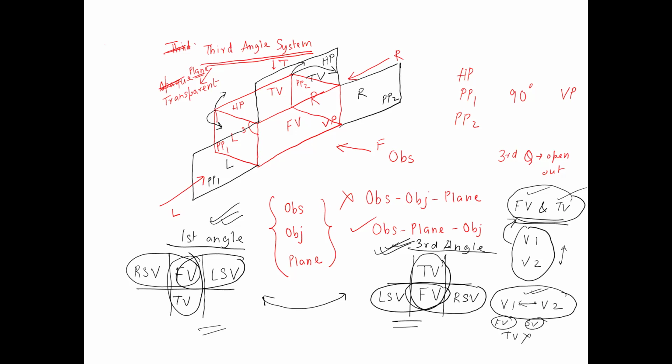So you have to indicate clearly in your drawing sheet somewhere the system of projection that you have followed, whether the first angle system or the third angle system. For that, we have a cell in our title block where we put some information about the system of projection. In the earlier drawing sheets on line types, lettering and dimensioning and on scale, where system of projection was an irrelevant concept, you did not write anything meaningful in that cell. You just wrote these 3 words.